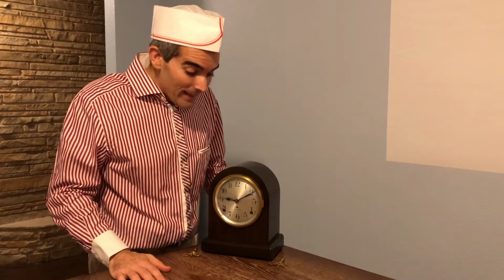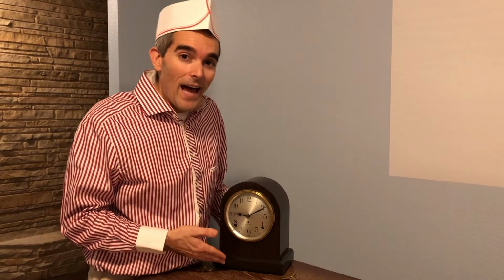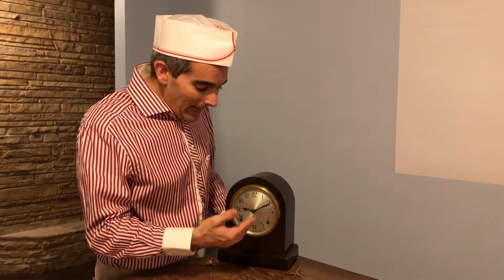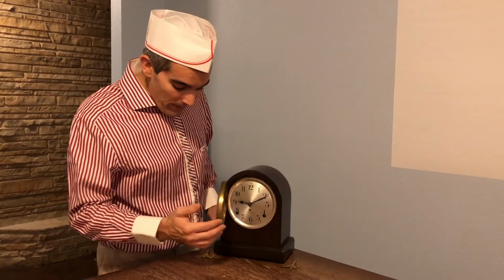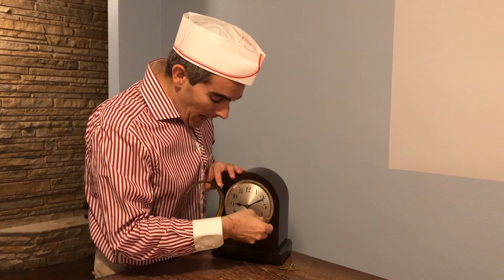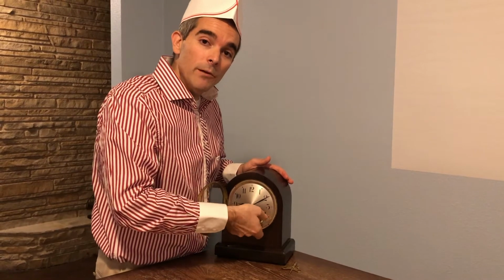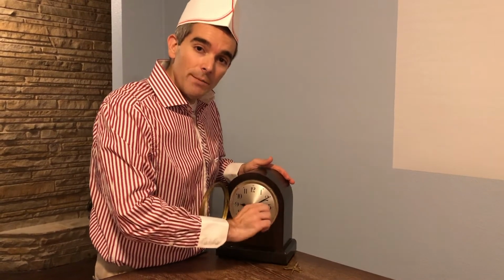The clocks are actually pretty cool, and they have a lot to teach us about gear ratios and power. Because believe it or not, this clock can run for 8 days with no electricity, no batteries, no nothing, just mechanical power. So how do we gain that mechanical power? Well, we have what we call a key. This key goes in here and we twist. And what we're doing is we're twisting a torsional spring.